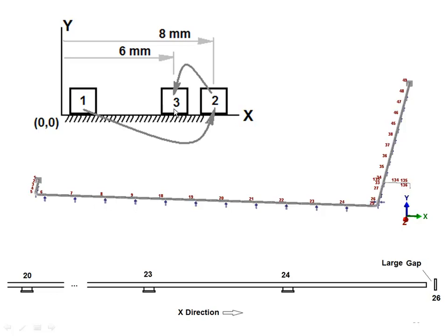For the example problem, since the gap was closed and some of the friction loads changed sign, the reaction loads at point 26 increased. Programs that don't evaluate the path dependence of the load won't see that the sign changed and can underestimate the load. Using a program based on total displacement for the friction load directions, the reaction load on the gap support at 26 was calculated to be 8,800 pounds. Using the PCL, which accommodates the path-dependent change in the load along the X run of pipe, the load was 14,000 pounds, or 1.6 times greater.